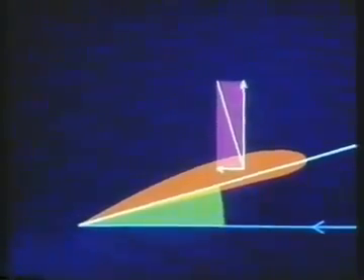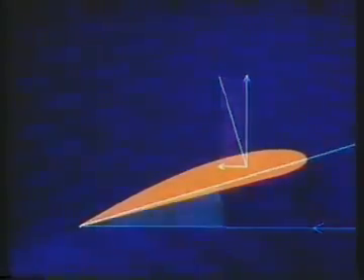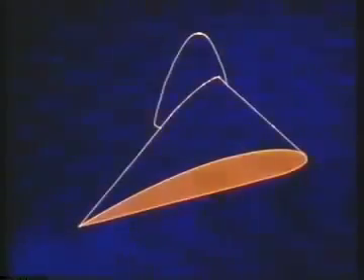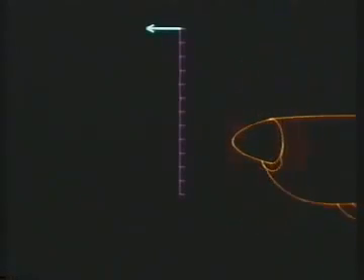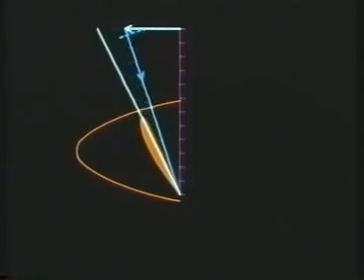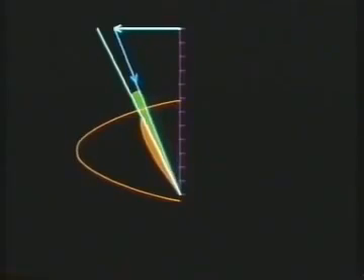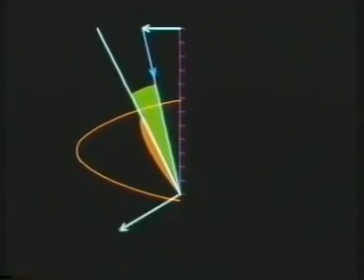But whereas the speed of the airflow over a wing aerofoil is dictated by the speed of the aircraft, the airflow over a propeller is governed by its rotational speed, which is much faster than the forward velocity and virtually constant. Consequently, changes of forward velocity have very little effect on the speed of the relative airflow. What is affected by changes of forward velocity is the angle of attack and the consequent strength and direction of the total reaction produced.